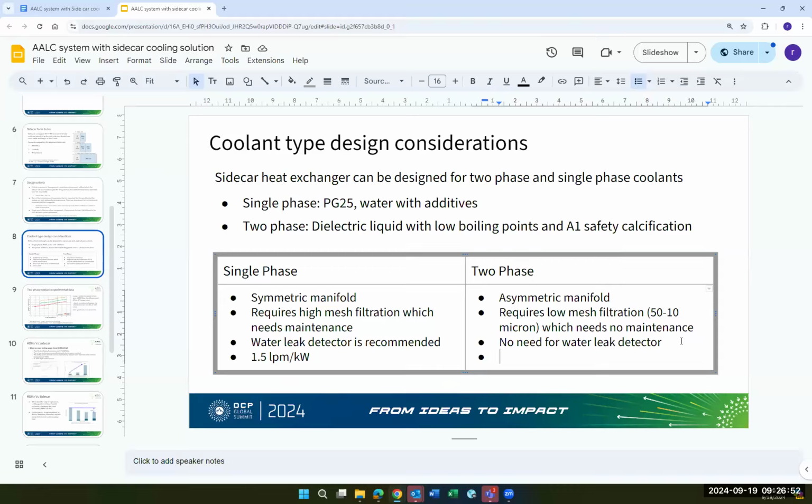I have a small question. What type of dielectric liquid are you speaking about? I worked a lot with dielectric liquid in immersion cooling applications, and in my opinion the kinematic viscosity is very high, and the power consumption is higher. You're talking about single phase immersion, not two phase immersion. Because you are writing now two-phase immersion. It's not two-phase immersion cooling in total.